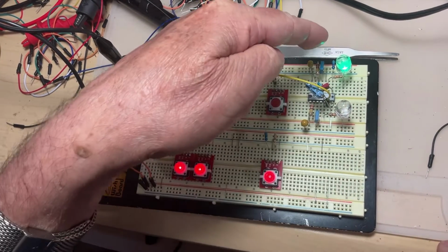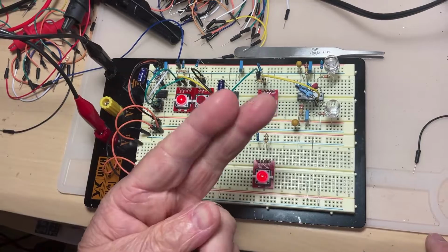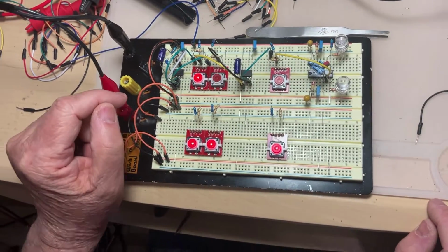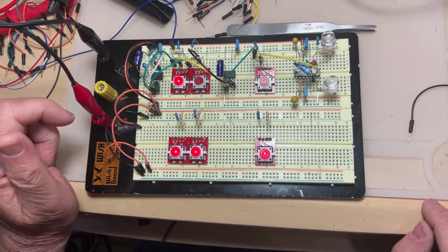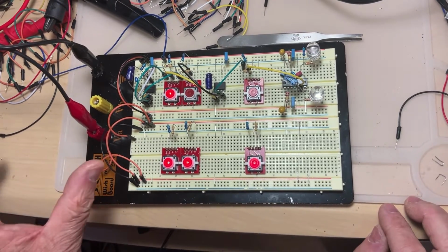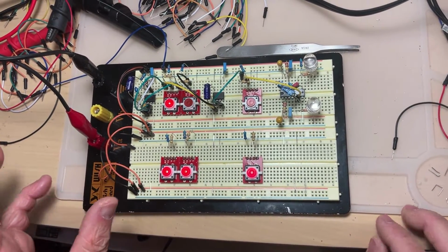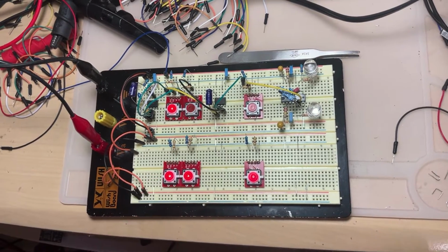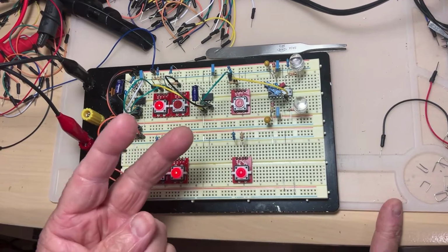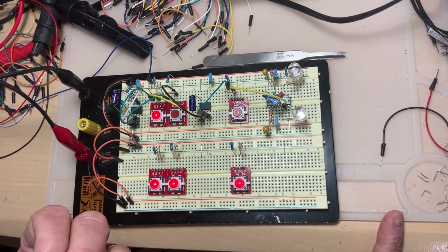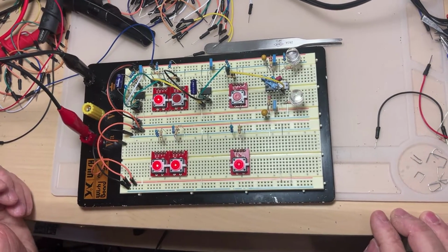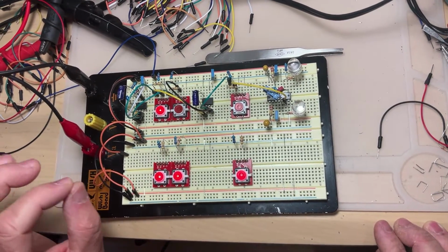And you can also trigger a second one if you cascade 2 packages together, or you put the package 556, which contains 2 555s inside the same package. As you noticed, the 555 has 8 terminals. 8 terminals times 2, it makes 16. But if you put them in the same package, you only need the power supply terminals 2 times. If you subtract 2 terminals out of 16, you have 14. So the 556 contains exactly 2 identical 555s inside.